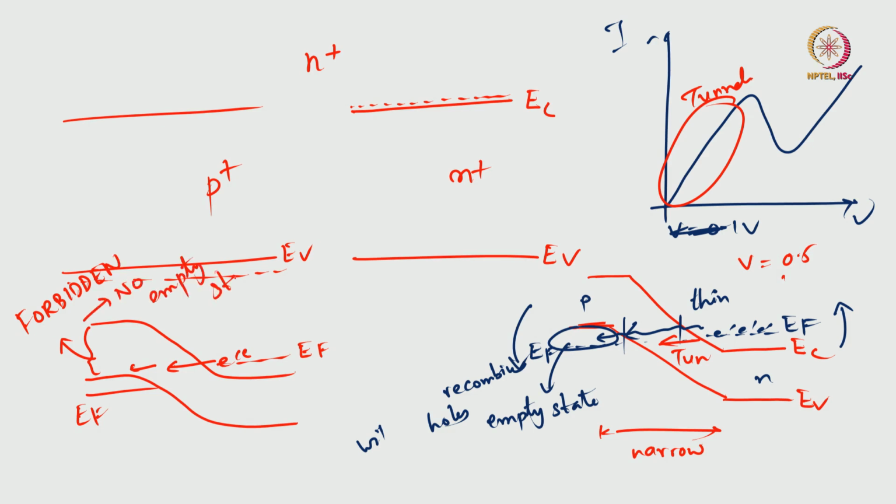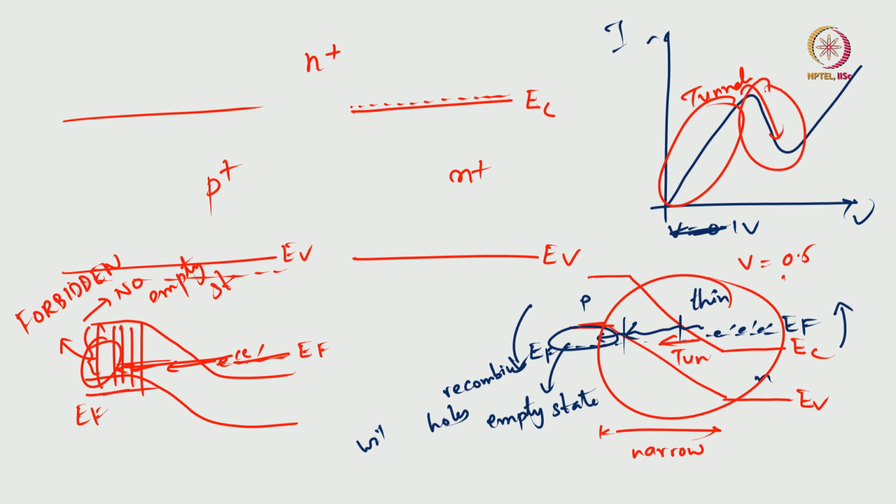So, what it means is that the electrons will now find it difficult to tunnel because there are no empty states here. So, the tunneling current will drop. Initially it was like that, where there are enough tunneling states, but gradually, because you are applying a forward bias, the band bending is happening. So, now the Fermi level is aligned to the band gap, the forbidden gap. So, electrons cannot tunnel, and so the current will keep dropping. Now, what happens after that, right?